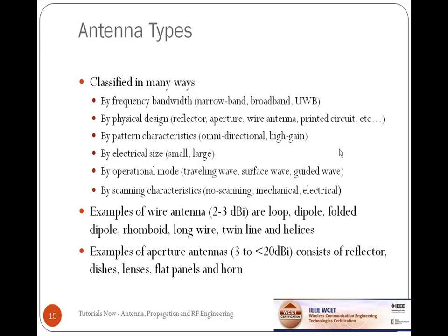They could also be classified by pattern characteristic, whether it's omnidirectional or a very high gain antenna. They could also be classified by electrical size, where they are small or large, or by operational mode, where they are traveling wave, surface wave, or guided wave. Or they can be classified by scanning characteristic, with no scanning, mechanical scanning, or electrical scanning.